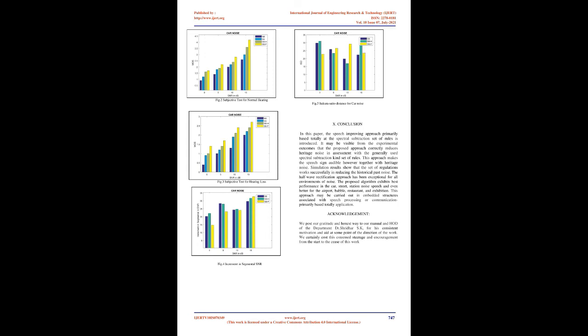B. Log likelihood ratio, LLR. It is one of the LPC-based measures of speech quality. The phase between the spectrum of clean speech and processed speech is calculated through LLR, which gives the amount of distortion added during processing. The log likelihood ratio test is calculated with respect to clean speech and enhanced speech. The equation used to calculate LLR is shown in the equation, where AE equals the LPC vector of the enhanced or processed speech signal, AC equals the LPC vector of the clean speech signal,